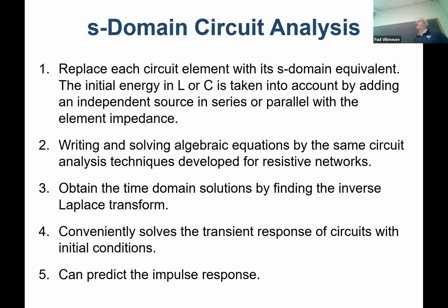That's it. R, L, and C circuits. That's all we have to worry about in this class, because those are pretty much all the devices you'll ever come across in industry. You might have some nonlinear devices. You might have a couple of diodes and whatnot, but you wouldn't necessarily be looking at them in this capacity. So what do we do? When we come to a circuit, we get rid of the R's, L's, and C's, and we replace them by the Laplace domain equivalent circuit.